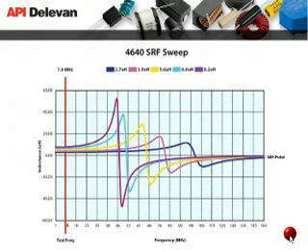The application frequency of an inductor should be no greater than 1/2 of the self-resonant frequency. So, if the SRF is 40 MHz, the inductor should not be used much over 20 MHz. Once above 1/2 the SRF in a circuit, a great variance in inductance is experienced, creating undesirable operating characteristics.